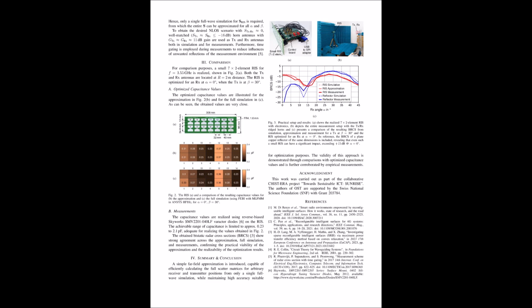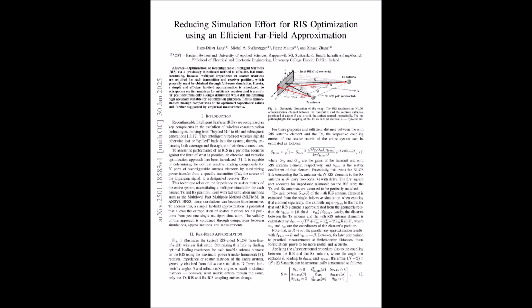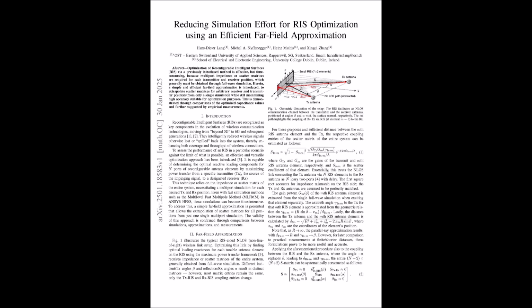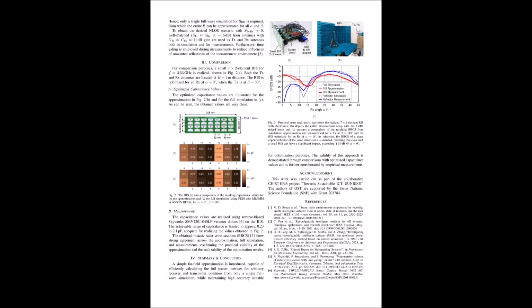The next part is all about the antenna gains. We have the square root of G_TX times G_M(θ_TX). Remember, G_TX represents the gain of the transmitter antenna, and G_M(θ_TX) represents the gain of the m-th element on the RIS in the direction of the transmitter. Okay, so we're essentially multiplying the transmitting power of the transmitter antenna by the receiving power of the specific RIS element we're looking at. The stronger each of these is, the stronger the overall coupling.